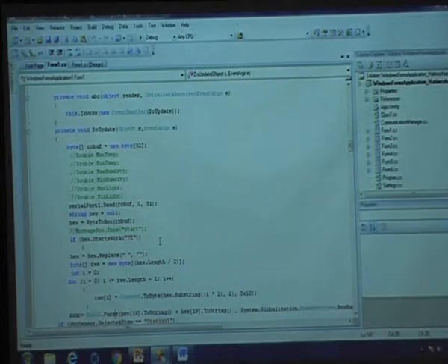So what is that? The condition I am writing in the program is that the received hexadecimal value is a 7E. Then what must be done? That is the first condition I am keeping in my program here. The received value is a 7E. Obviously you know that the starting delimiter of my frame is 7E.